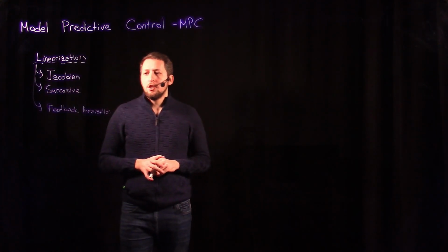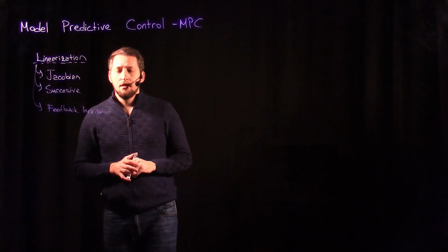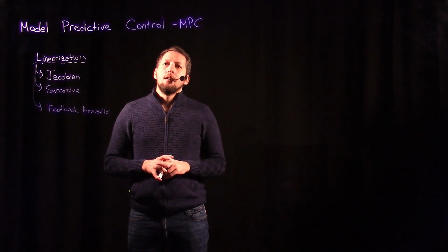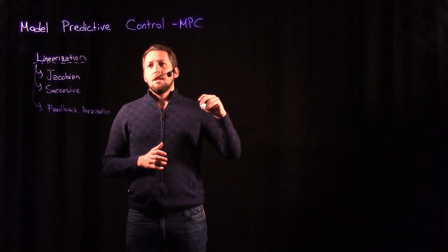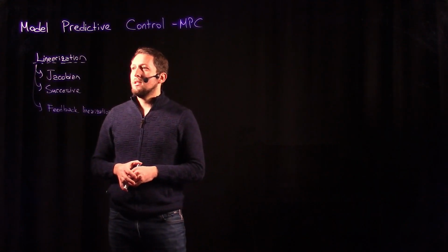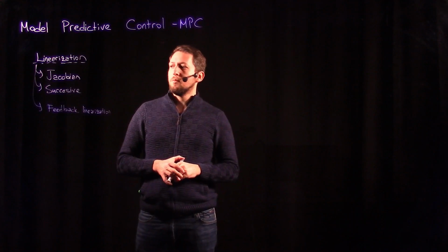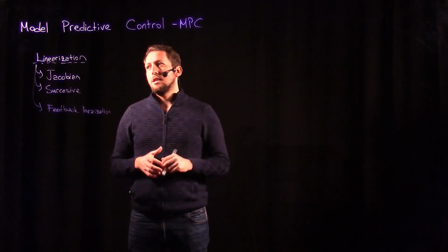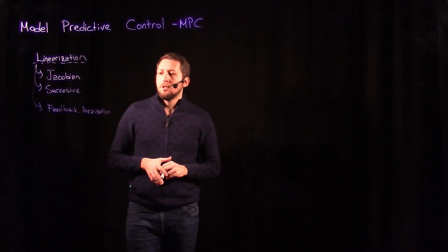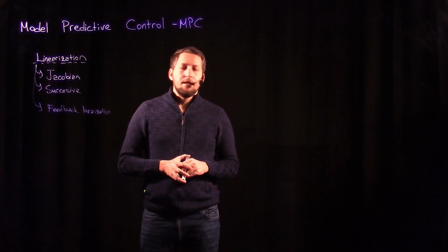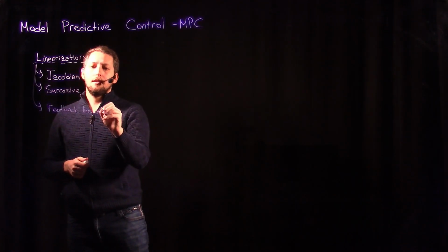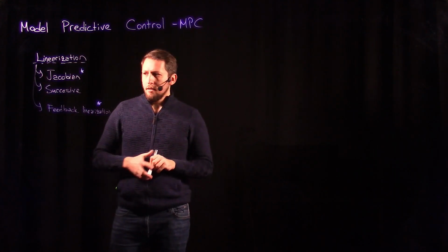And feedback linearization, there are also two options in the feedback linearization, state and output feedback linearization, but it targets creating some new fictive variables and a map between your current states and new artificial states. So the overall system between this fictive input signal and the actual states or actual output shows itself as a linear system. And this last one, feedback linearization, proposes better options in terms of practicality. Okay, so then let's slightly dig deeper into the Jacobian and the feedback linearization parts today.